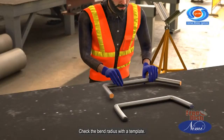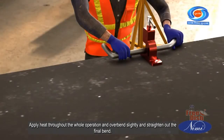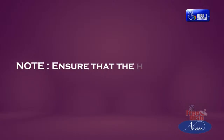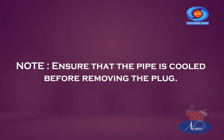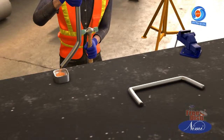Check the bend radius with a template. Apply heat throughout the whole operation, overbend slightly and straighten out the final bend. Remove one end of the plug. Note: ensure that the pipe is cooled before removing the plug. Remove the sand by tapping the pipe gently with a hammer.